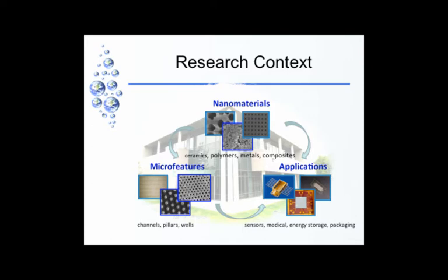So that particular microchannel plate that you see is the starting point for a portable kidney dialysis machine. And they have microscale features which are between 100 microns and a couple of hundred microns. And the membrane that we made is a powder polymer composite, cellulose nanocrystals, which are hydrophilic, in a polysulfone matrix where polysulfone is blood compatible.